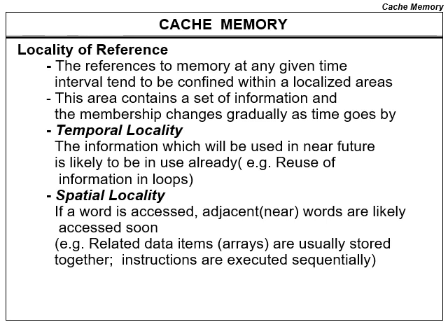Temporal locality basically means the information which will be used in the near future. Temporal is related to time. What it means is that suppose I have accessed a particular instruction or a piece of data at this point in time. Now the instruction that I will be requiring in the near future. See, here is a time element over here. The information which will be required in the near future is likely to be in use nearly, right? So for example, loops.